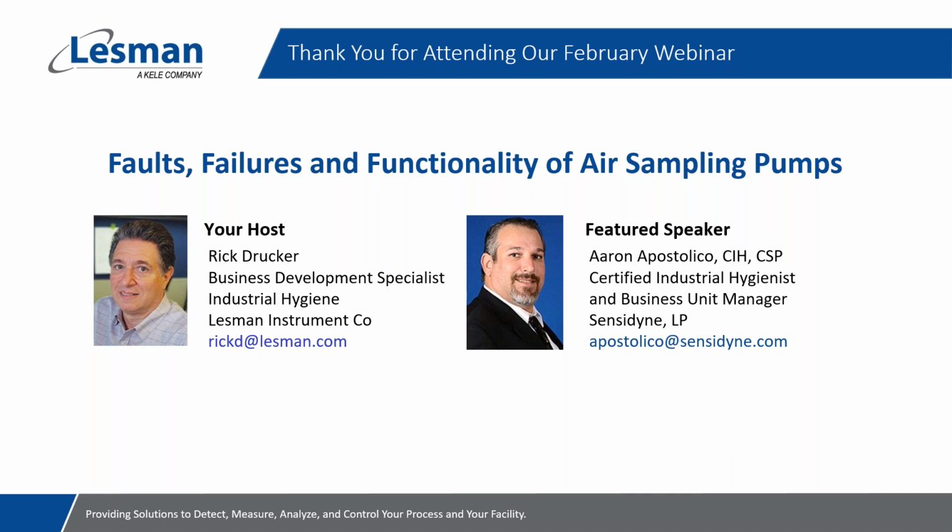which are particle impactors. So if you're using a size selective cyclone or impactor, there's already some back pressure created by that. If you got loading or heavy dust in those pores for the PPI, it can actually clog up that PPI and cause the pump to fault out. Other scenarios that I've seen in dust collection, there were certain operations with unloading of trucks that had a lot of dust going on, even rail cars that were being unloaded with really high plumes of dust.